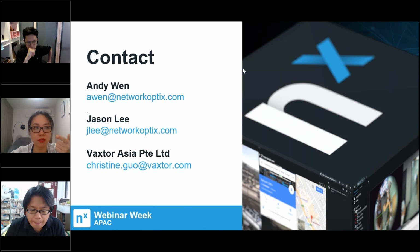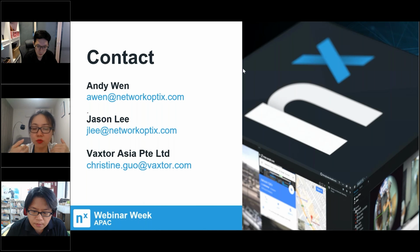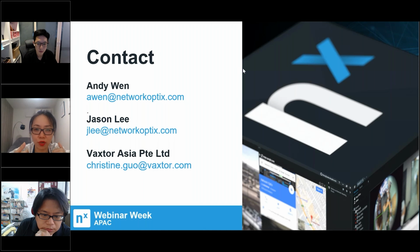In terms of specification, for a lot of professional ALPR cameras, older versions have a resolution of perhaps only 720p or even lower. But we still can use that, no problem. But we always emphasize the lens. The optical lens is critical for us in order to have the pixel density, which is much more useful than a high resolution. I would rather you give me a good lens than a 4K camera, which is cheaper for you as well.